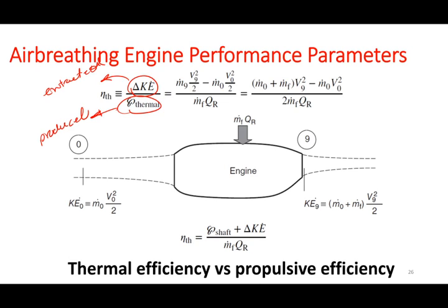The total heat input of the system in the denominator is something that's generated in the combustor within the engine, right? It can be calculated from the amount of fuel that is put in and the total heat rate that you are getting from the combustion of that specific fuel, right? This is a parameter that you usually can get for the fuel that you are using, the QR.